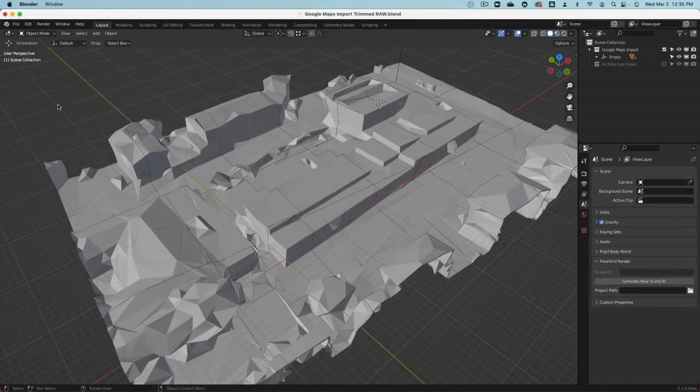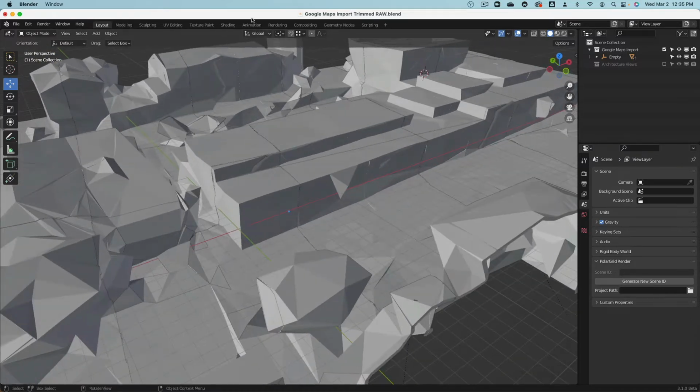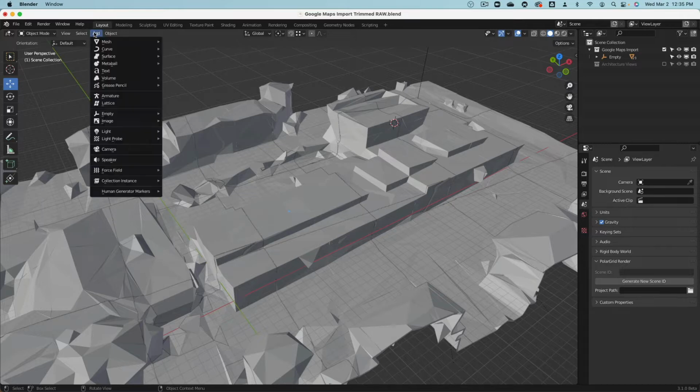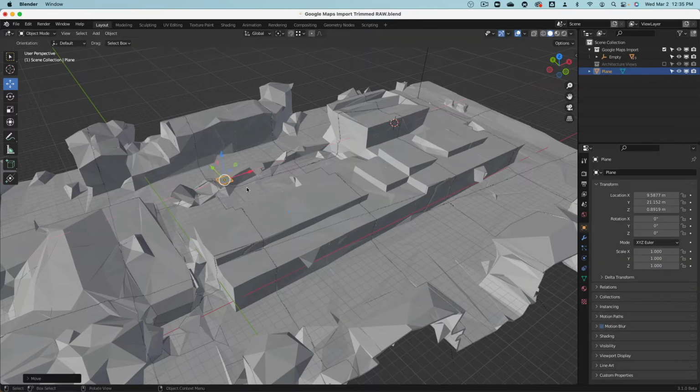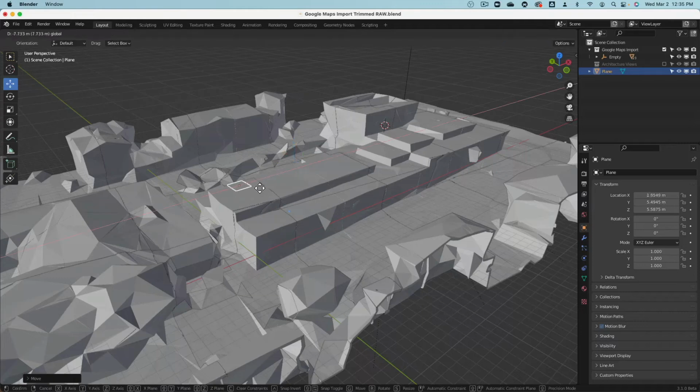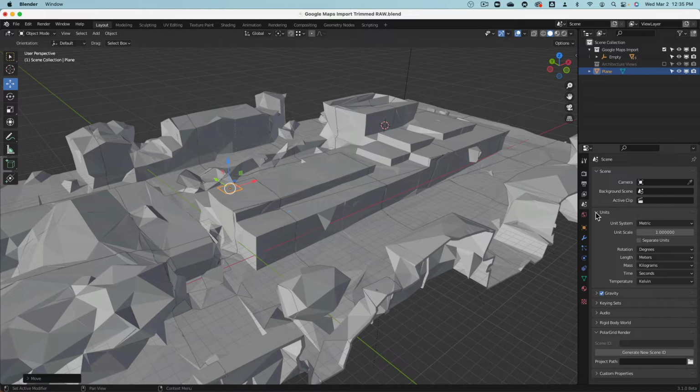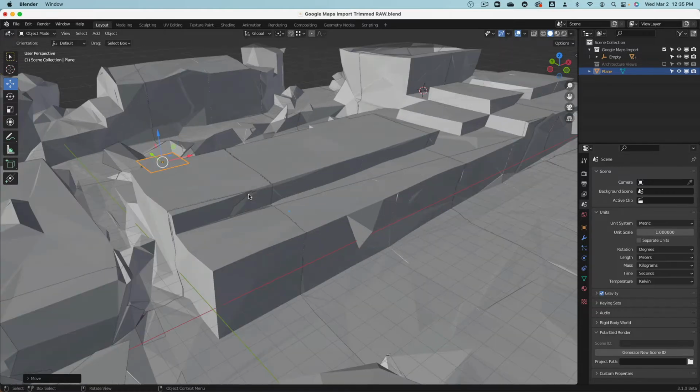And let's press T for the toolbar. And the snapping, yeah, it's set to vertex point. Very good. And then let's press Shift A for add, or add mesh plane. There we are. And then we drag this to somewhere here. The unit system, by the way, since this is a project in Spain, is set to metric right now, meters.